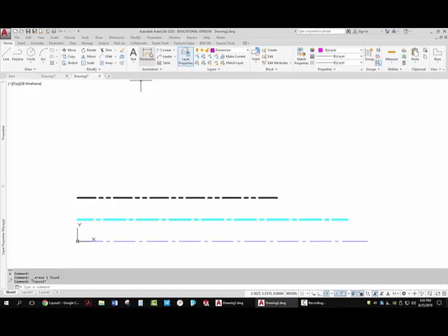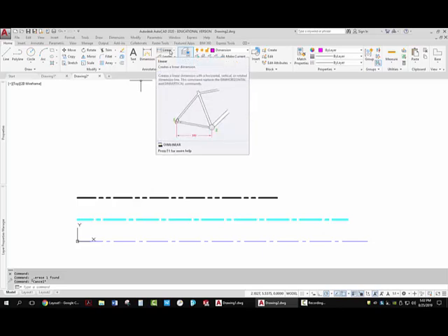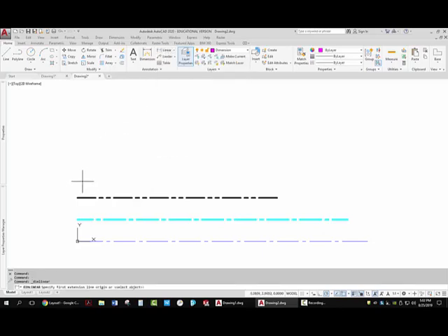And all the dimension tools are also available on the ribbon. You can come up here and just pick dimension, which actually somewhat automates the process. Or you can go and pick linear, or you can type DLI for dim linear. If I pick linear dimension, I'm going to hover over the end of this and go up, and I'll still go 0.75. Now that's where my dimension starts. If I go off to the right, 6.875, you'll notice it's exactly the same length as the cutting plane line.